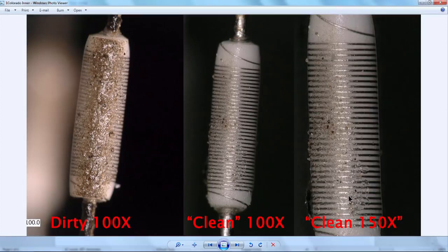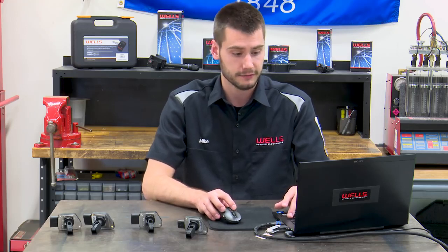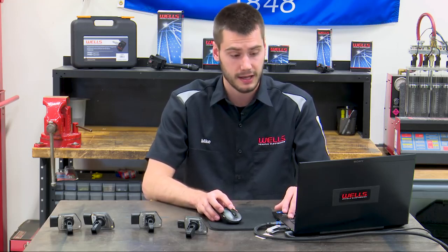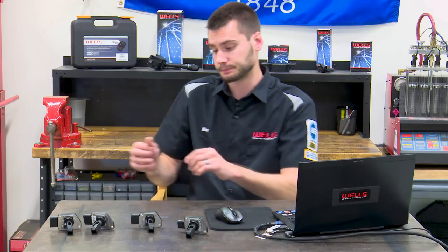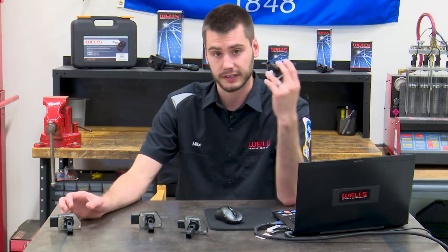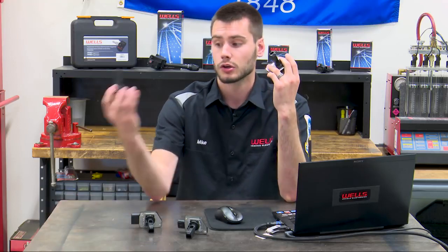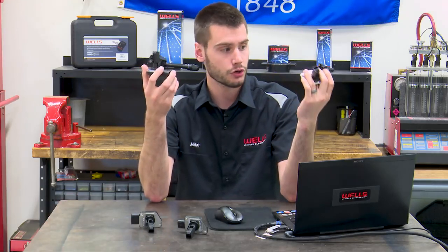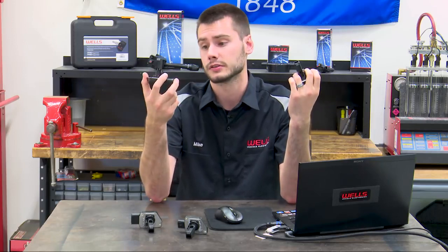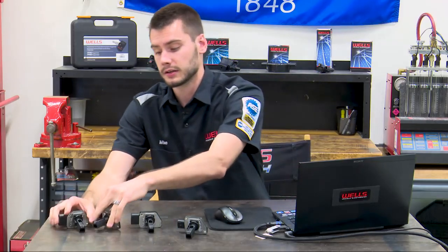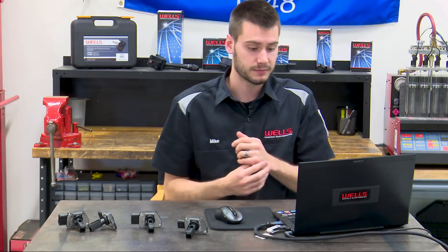So, in my opinion, the best way to fix the vehicle would be to replace the mass airflow sensor, and that's going off of the evidence that I have here in front of me. Now, when replacing the sensor, you've got a couple options. You have one like this, which is a reman sensor, or a brand new sensor. So there's a price difference, obviously, rebuilt versus brand new, but is there a difference with the elements themselves?